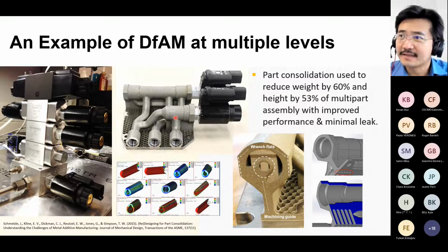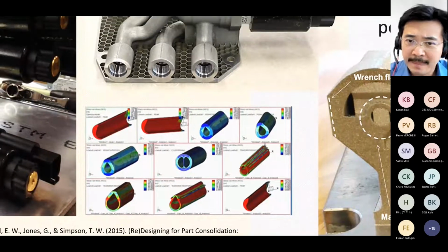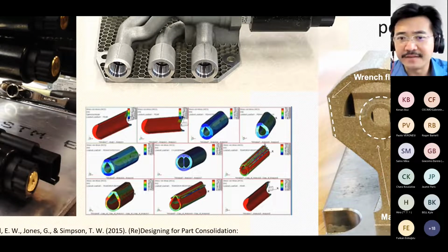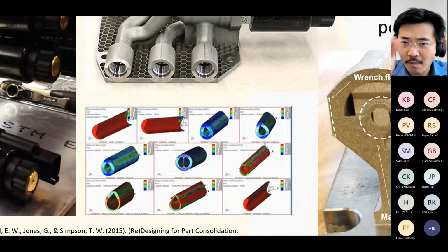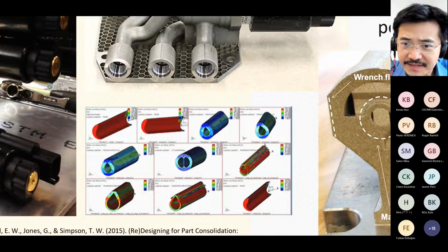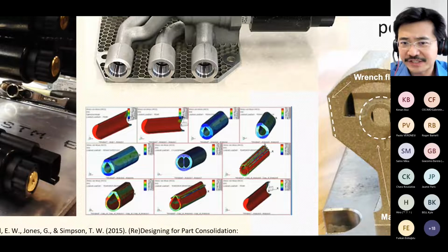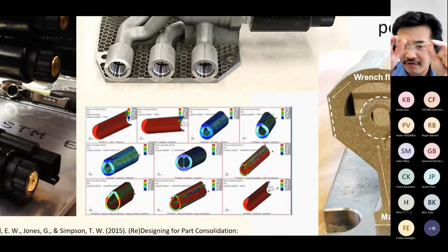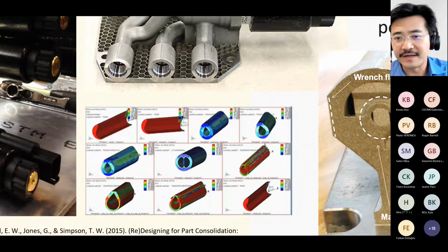And as you can also see, the internal details of the channels. In the channels, they have also managed to achieve different types of cross-section for the internal channels, which is not going to be achievable by normal means. They've also applied FEA, because they have tried to produce that through standard uniform walls, as well as through teardrop shaped walls. In the teardrop shaped walls, they apply FEA, and you can see some parts which would have a lot of stress. In some parts they have tried to thicken it. By thickening them through variable thicknesses, they have made some parts stronger than usual. Otherwise, obviously, you will not be able to achieve the kind of part integrity.